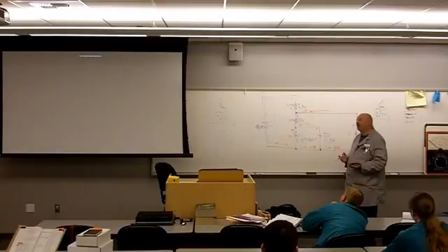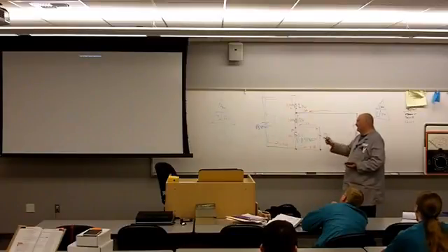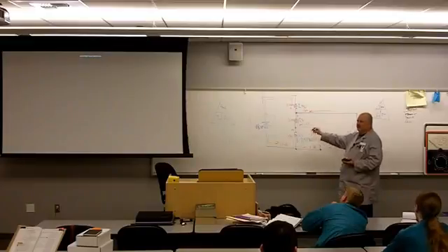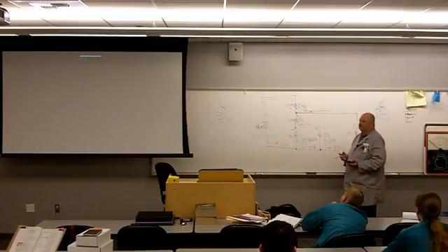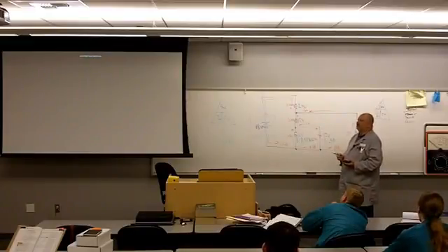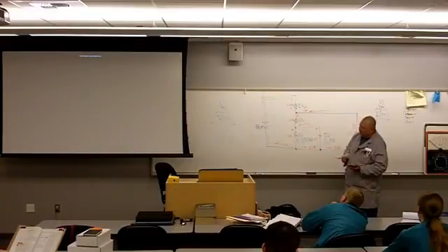What happens if your resistor only actually has 8 ohms if you get that big of a tolerance? You're going to get less of a voltage drop there, because that is kind of critical. The bigger the resistor, the bigger the voltage drop. The smaller the resistor, the smaller.